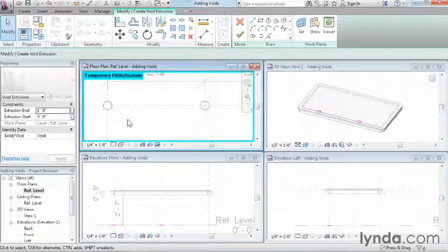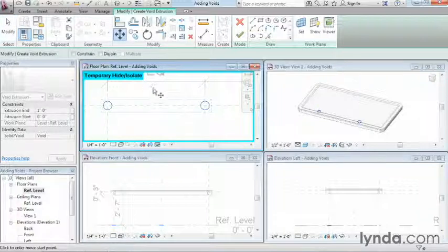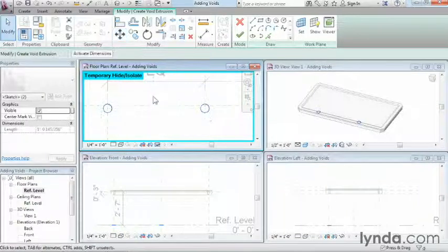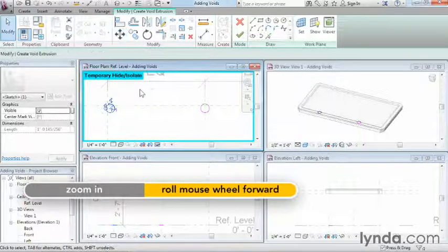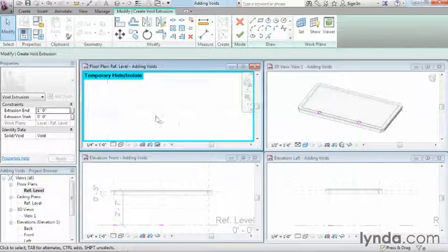I'm going to go to Modify, cancel out of there, and I'm going to select both of these, and I'm going to move them down, and I'm going to just click any start point, start moving down, and then I'm going to type in 1.25 inches. Then I'm going to select only this one, go to Move, start moving it to the right the same amount, 1.25 inches. So this one is shifted in from the center line in both directions.